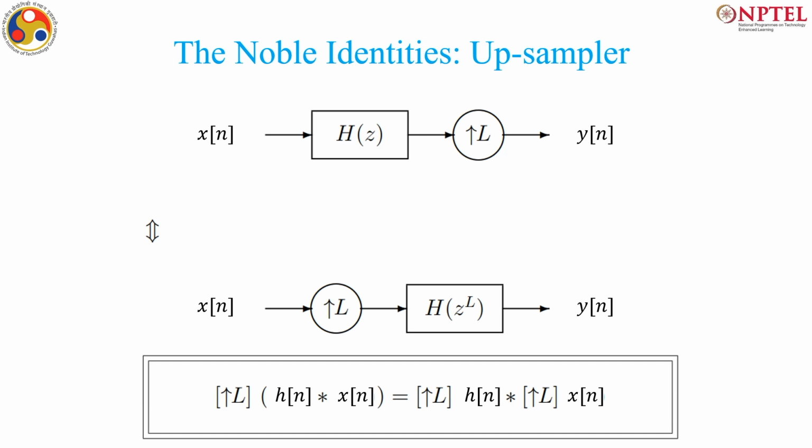So, if you see this structure, what is this? This is an interpolator. So, we first upsample by a factor L, and then we use the filter to remove the spectral images. Of course, if you find this difficult, you should go and watch the previous lecture, multirate signal processing 1, because this is a continuation of that.